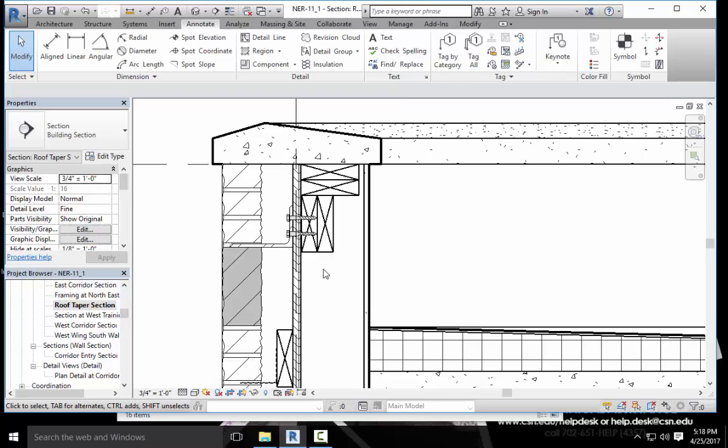Now that you have a good grasp of adding detail components, you need to learn how to control the line weight so the outlines of the brick look a little bolder. If you remember, some of the detail components were modified based on the line weight of the filled region perimeter. This thickness was changed from heavy lines to detail items. You need to set detail items to a thickness you can live with.